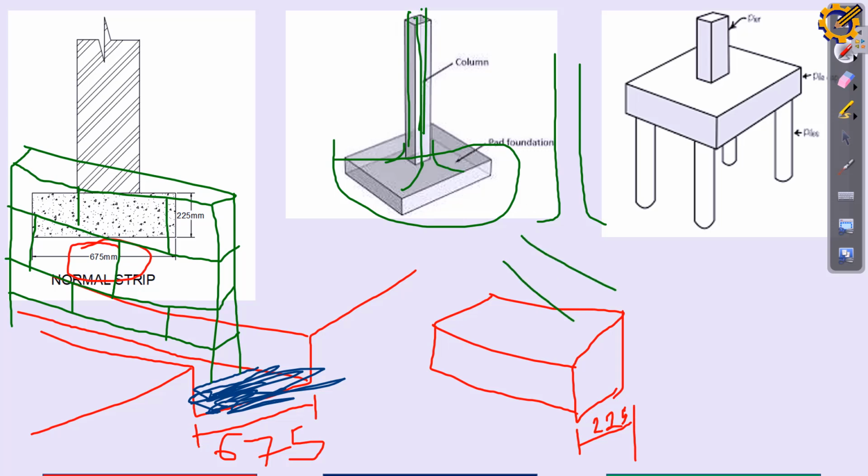And there will be something called a mat, which is laid like this. It is reinforcement also. They bind this, and the L-shaped legs sit on it like this, 1, 2, 3, and 4. They carry it and place it on that area, then pour concrete. So the whole of that is called a pad foundation.